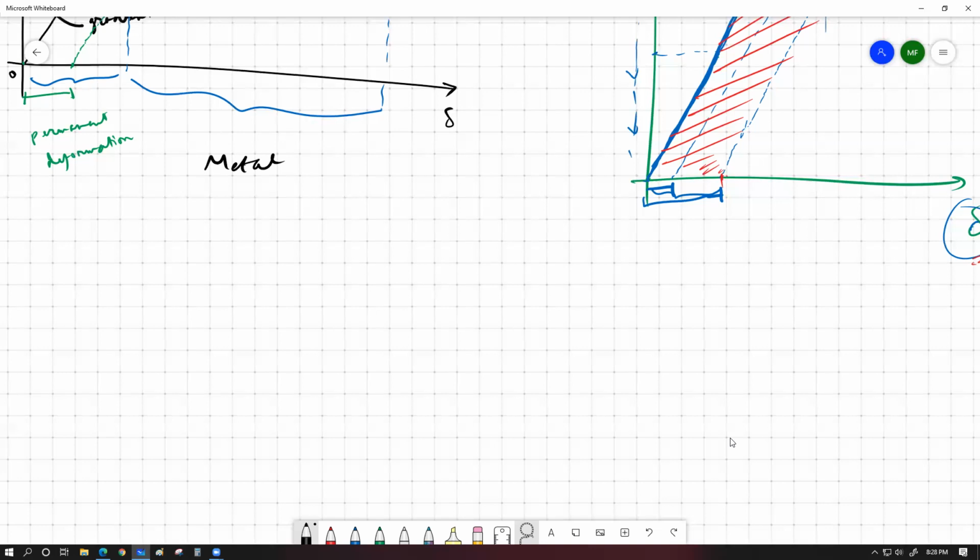So if you draw a force versus extension graph, you might get a pretty steep line, but it's going to be mostly a straight line. The moment the glass specimen goes over the very small amount of elastic deformation that it allows, it starts to crack. And the moment it cracks, all of the glass shatters. That's how glass is made. So these are the two different types of materials that you want to recall from your understanding.